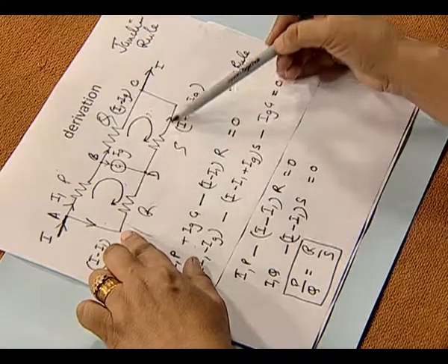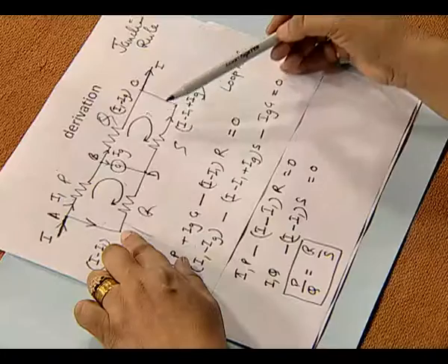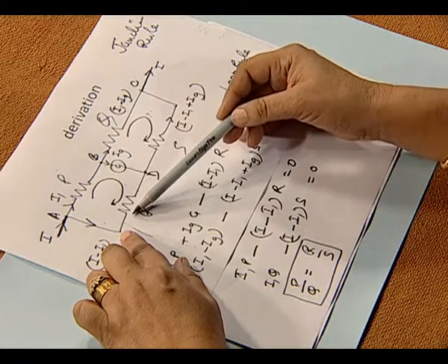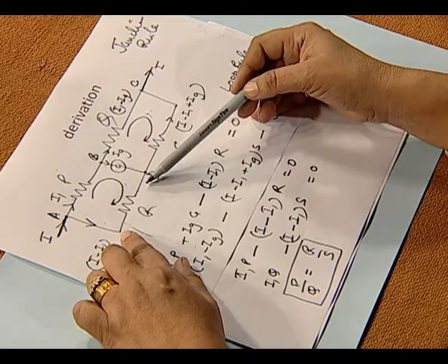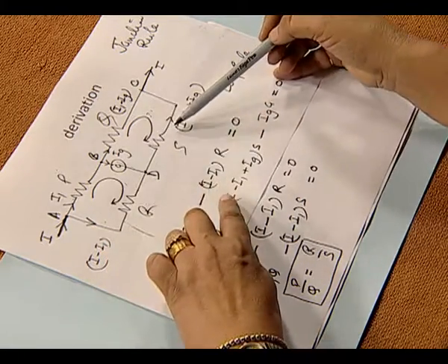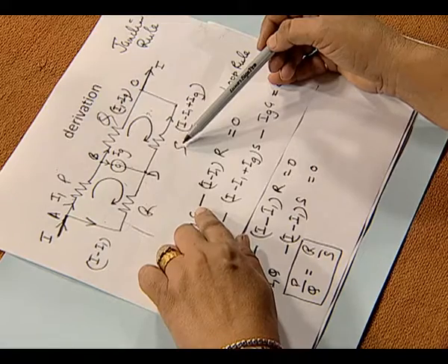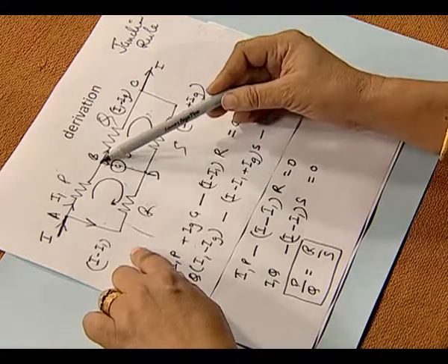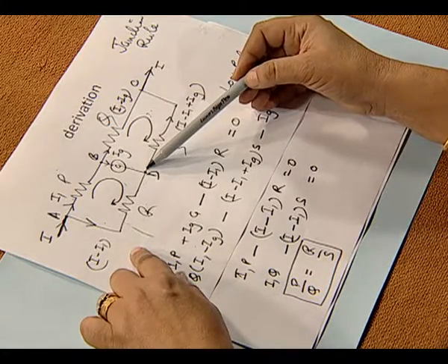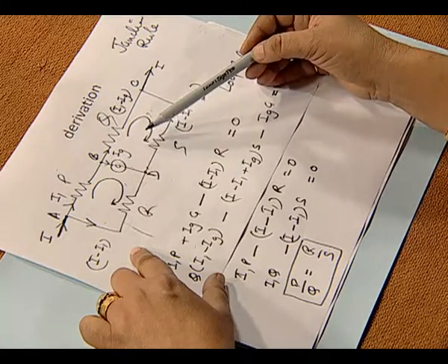Instead of R and S, you have a 1 meter long wire, and a jockey can tap it at different positions. Therefore, the length of the wire involved will contribute towards R, and 100 minus that length will contribute towards S, and therefore the same condition is established in a meter bridge, and that can be used to find the resistance of any conductor for which we do not know the value, but you will definitely need another conductor for which the resistance is known.